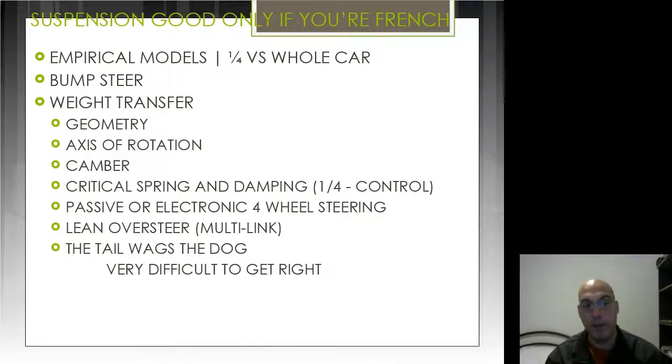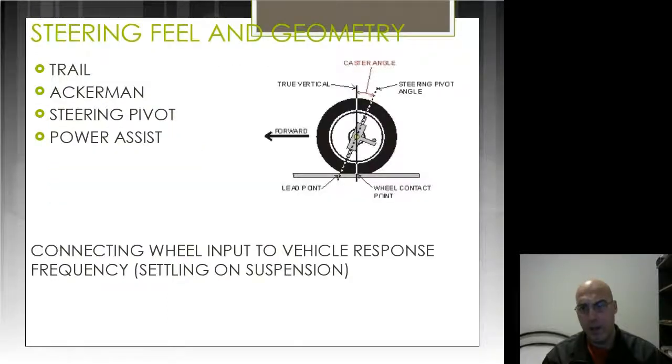Steering feel and geometry. Yeah, again, I say here it's very important how to connect the wheel input to the vehicle response. Is very important. With the roll centers, also something important is the roll centers of the suspension, and what height is the roll center, and how the vehicle settles when it turns into the corner. However, for me and my experience with my vehicles, after I put a lowering kit and